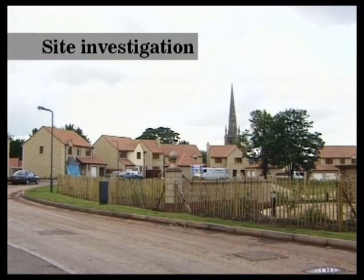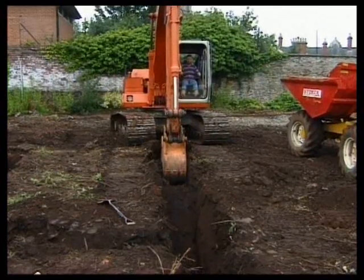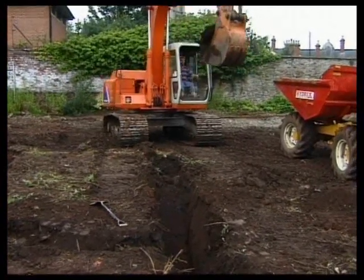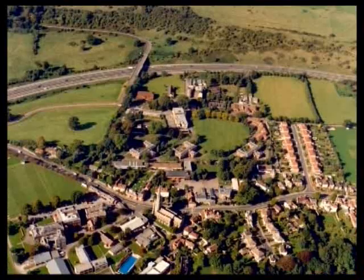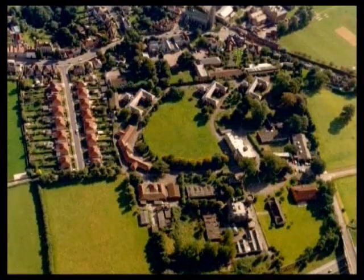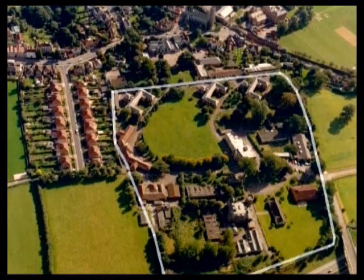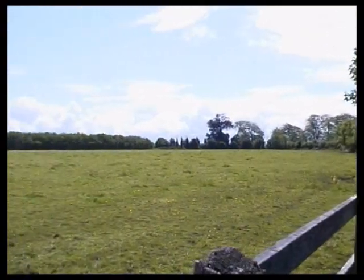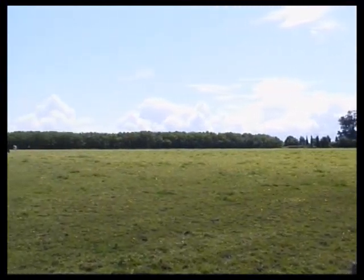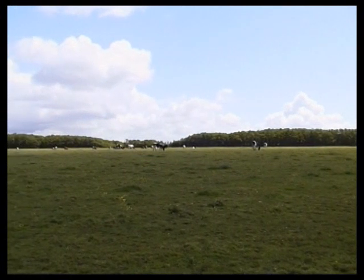Before foundation design and construction can begin, extensive site investigation is required. This normally involves three basic stages. The first is a desk-based study using existing documents, maps and photographs to help determine the history and conditions of the site. The second stage is a walkover survey, giving the designer the opportunity to identify the nature of the ground and any potential hazards.